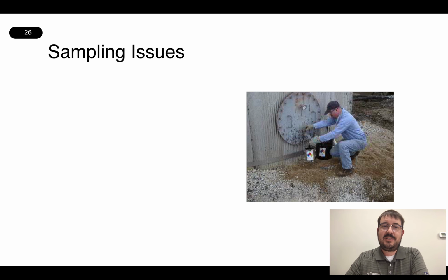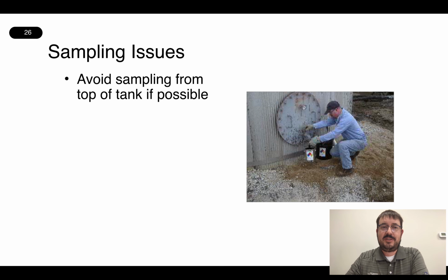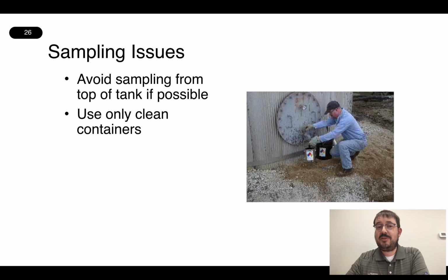So let's identify some potential sampling issues. It's recommended to avoid sampling from the top of the tank if possible. It's highly recommended to use only clean containers. This would minimize any risk of cross-contamination with other binders or other fuel type sources.